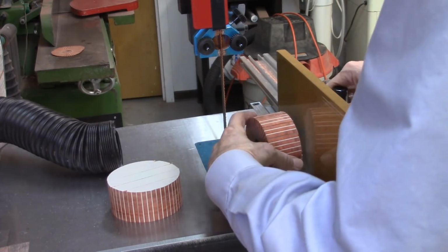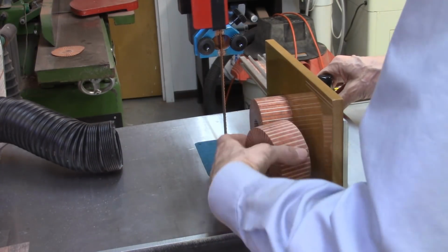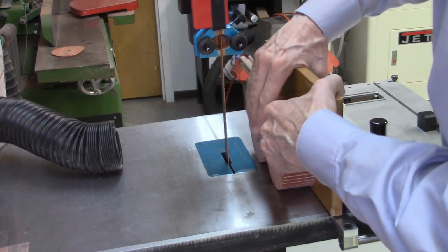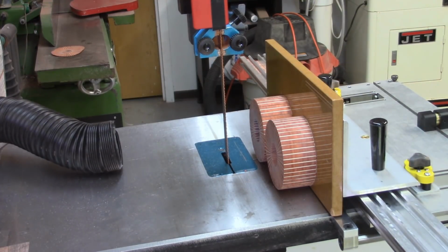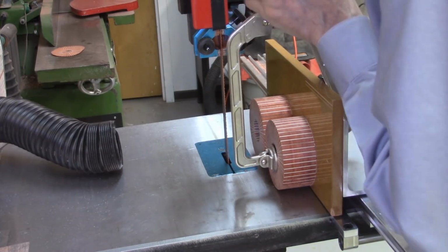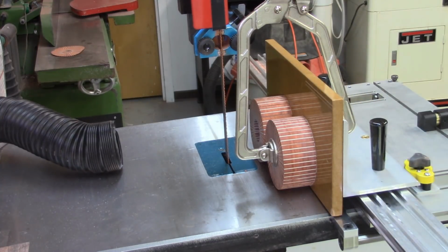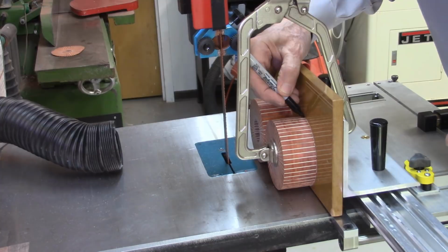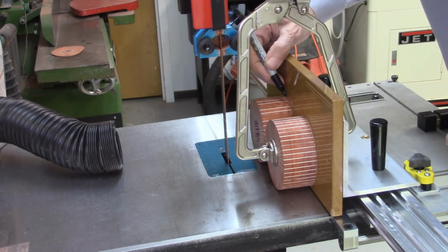I apply double-sided tape to the segmented disc assemblies and then attach them to the carriage on the Accu-Slice system. To speed up the operation, I mount 2 or 3 discs onto the carriage at the same time. I mark a line in each of the discs with a pencil or marker. This line is later used to realign each of the thin segmented discs during the glue-up process.